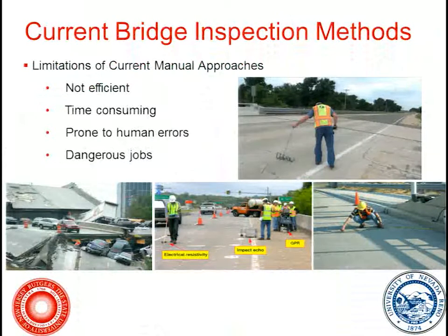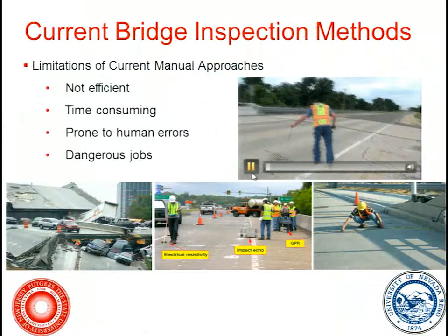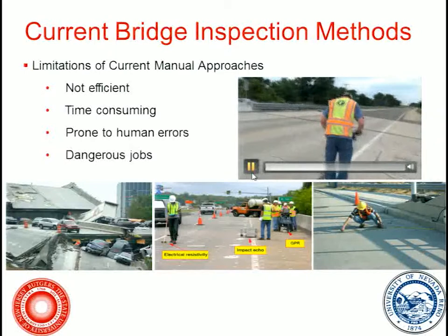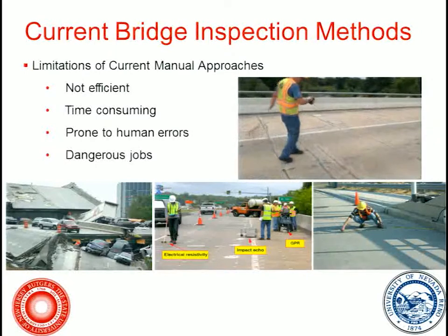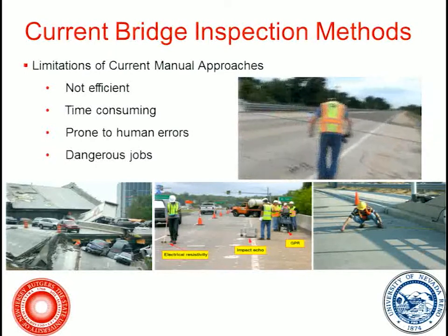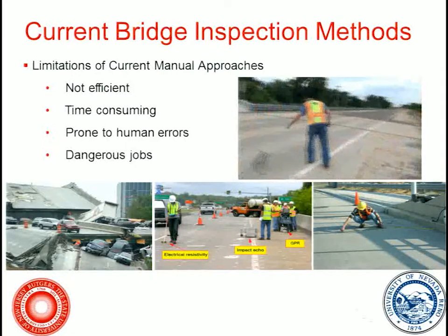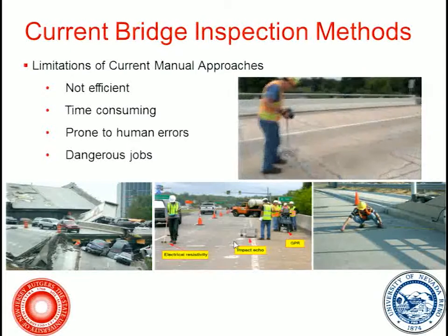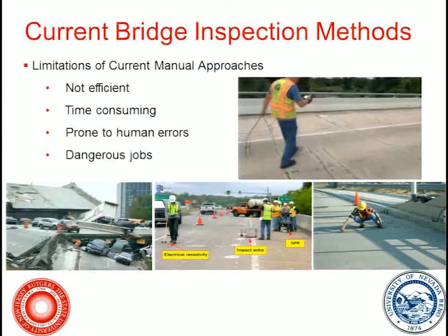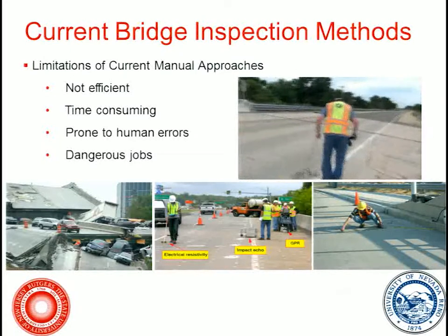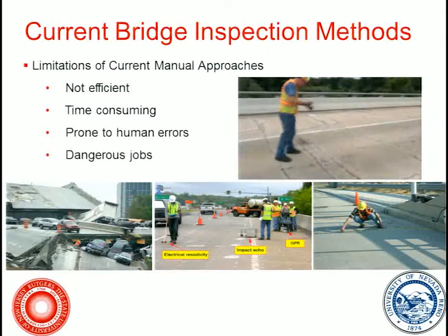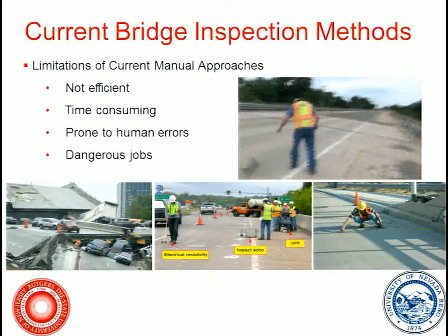Unfortunately, bridges are manually inspected. For example, as you see in this video, we have a very well-trained engineer who drags a chain along the bridge deck and detects the defect area by listening to the abnormal sound, or we have a bunch of people carrying different NDE sensors to inspect the bridges. This kind of method is not efficient, time-consuming, and also prone to human error. And of course, it is a very dangerous job because of open traffic.